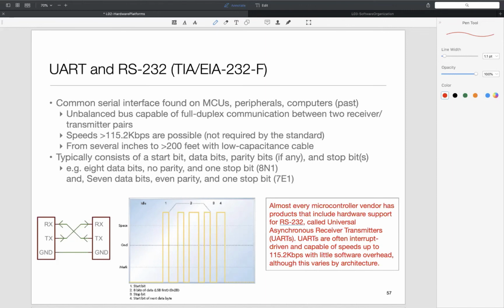But you do need to configure the different sites so that they're using compliant protocols. How many start bits are there? How many data bits are sent in one go? And are you sending any error checking parity bits or not? Very routine, and hardware and software implementations abound. So it's a very common way of connecting things, and as I said, oftentimes now we send UART over USB.